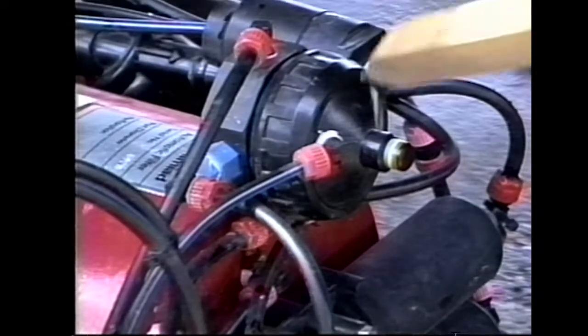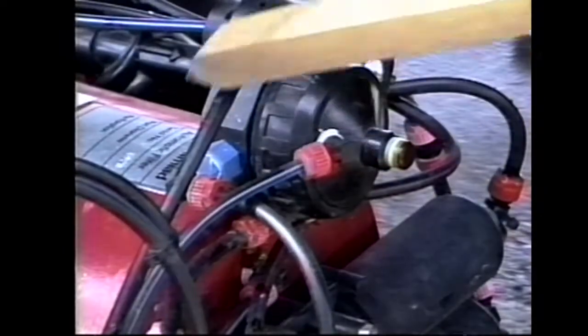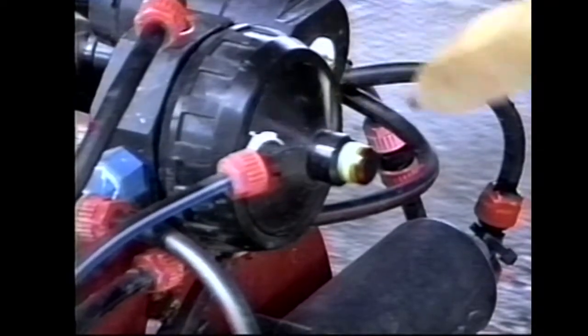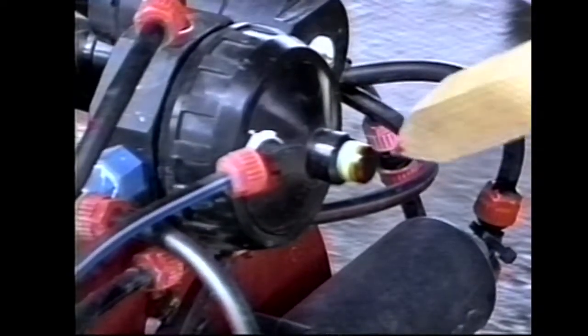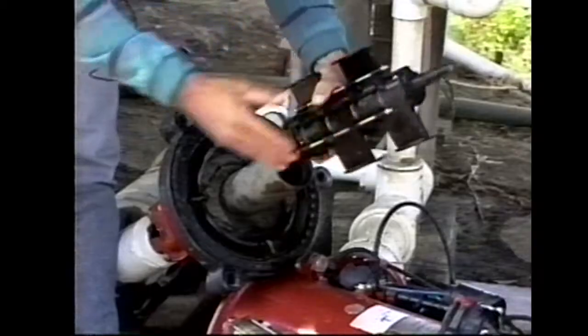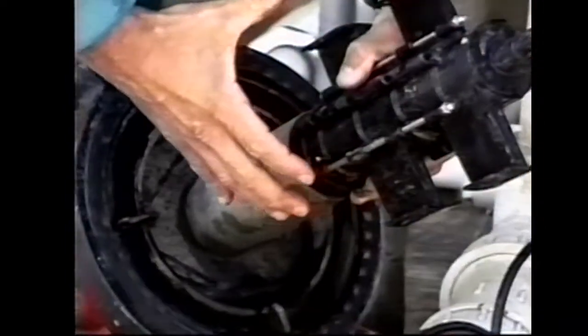Hydraulically actuated filters have a differential pressure switch. The differential pressure switch reads high pressure, indicated by the blue striped hose, and low pressure, symbolized by the hose with the red stripe. Once a pressure differential of 7 pounds per square inch is sensed, the multicolored button shown here recedes. The suction scanner is hooked to an exhaust valve which discharges into the atmosphere.